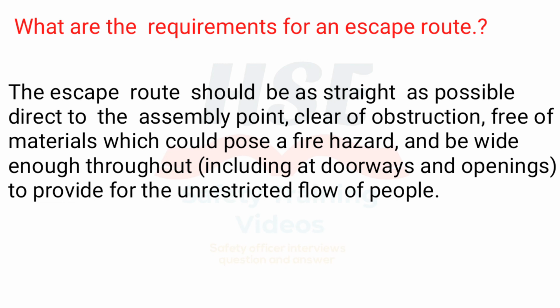What are the requirements for an escape route? The escape route should be as straight as possible direct to the assembly point, clear of obstruction, free of materials which could pose a fire hazard, and be wide enough throughout, including at doorways and openings, to provide for the unrestricted flow of people.